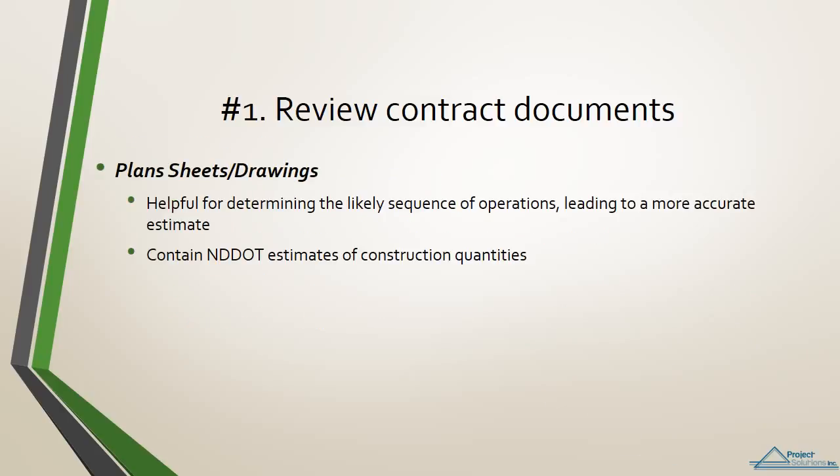Plans and drawings. Plans and drawings for a project should receive focus only after the specifications have been thoroughly examined and understood. The contractor will then have a better idea of what to look for on the drawings. Most state DOT plan sets also include estimates of quantities, which are necessary to perform a quantity takeoff. We will discuss quantity takeoffs later in this module.